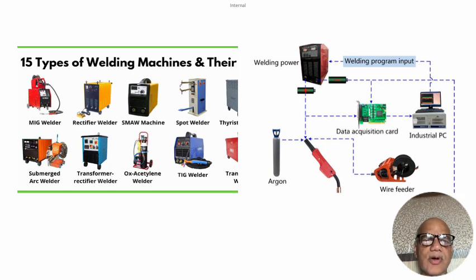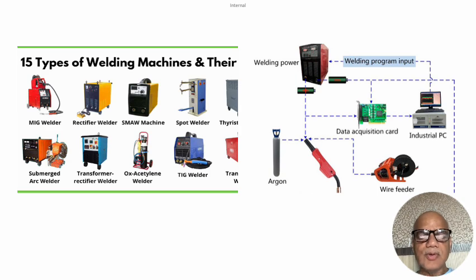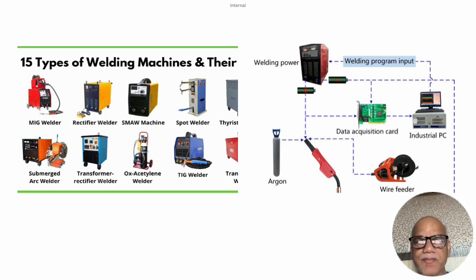We also use oxyacetylene welder. It's not electric, but there you use a fuel and oxygen, and fuel is normally acetylene, but many times we use LPG, CNG and other types of gases also as a fuel. Create a flame burning the fuel with the oxygen, and adjust the temperature, the flame width, height, dimensions, and depending upon the thickness of the plate and the filler wire, you can select the type of flame and the intensity of the flame.